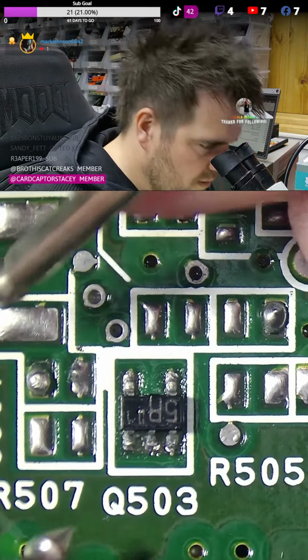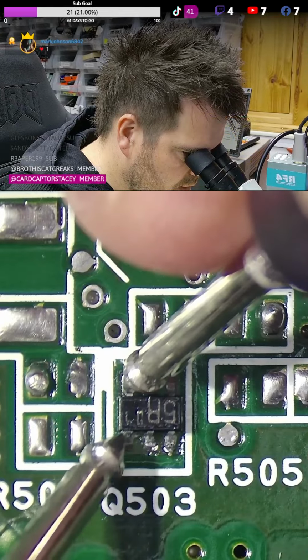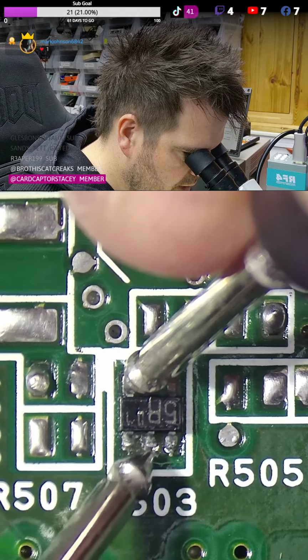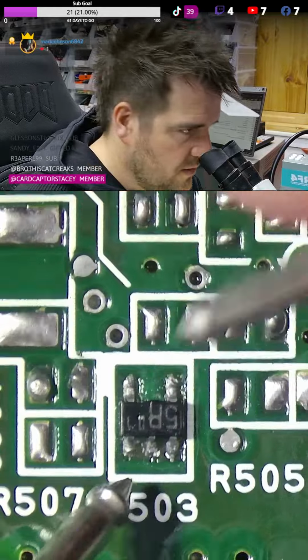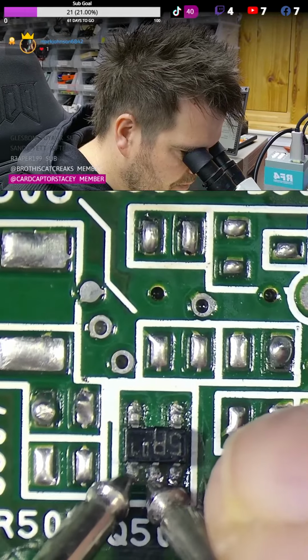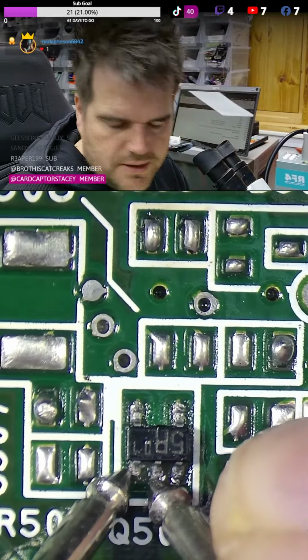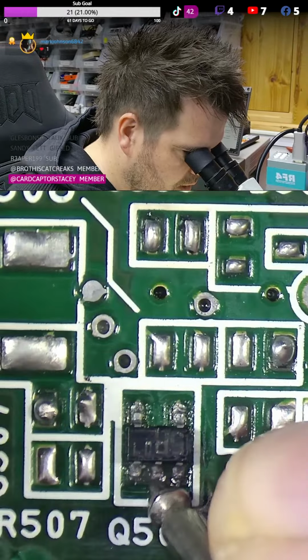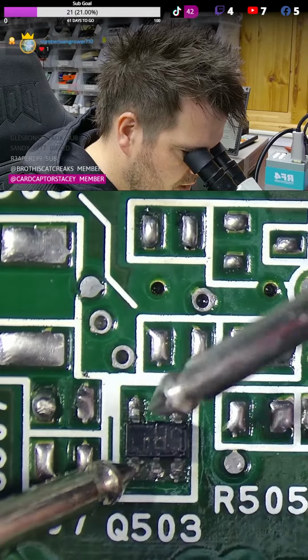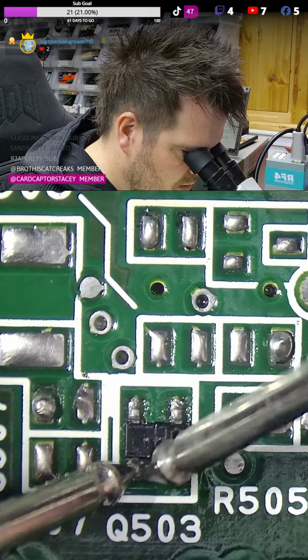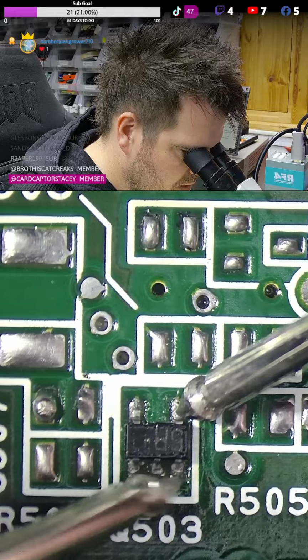Let's try this pin, the other side. I wonder if it's just, this could be a Darlington transistor maybe. So there's an NPN there. And there's nothing there. So I'm guessing this middle pin is going to have a cathode there. So we've got a cathode, two cathodes, three cathodes, two diodes.